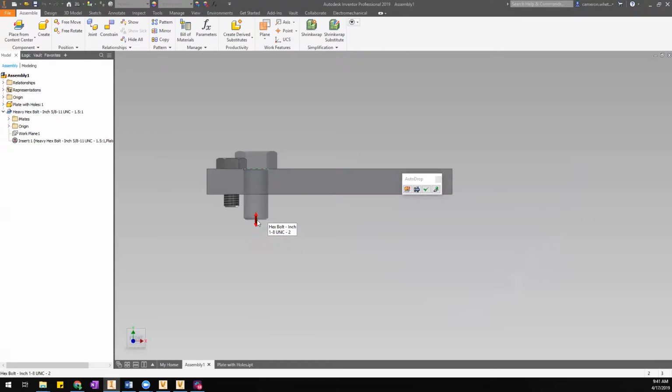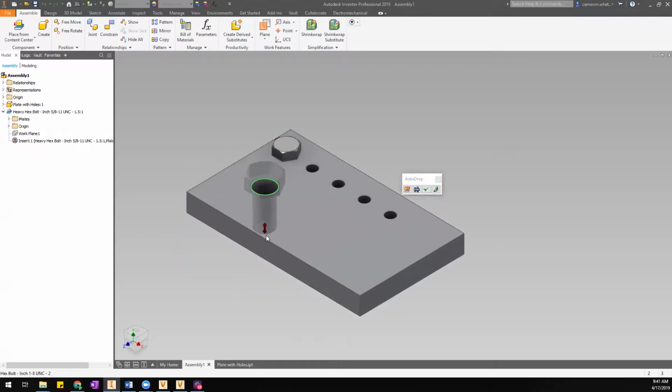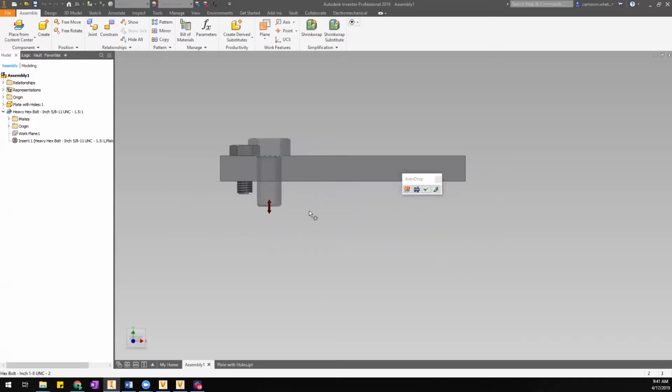You'll see it tells you in that little tooltip that pops up, there's 3-inch, 2.75, 2.5, etc. And that's grabbing stuff from the table. It's not a free length pull that just gives you some arbitrary number as you pull it down. Every time, as you can see, it's jumping in steps based on whatever's in the table.